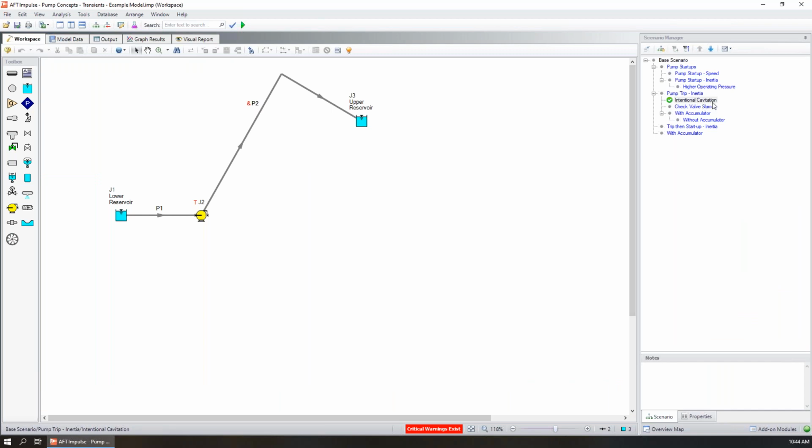So just a good example from a logical standpoint, from a physical standpoint, considering the system. If you remove this driving force, what the fluid wants to do is it wants to drain out this way, but it can't do that because there's not enough supply flow on this side. So instead what happens is the pressure drops at this point, it'll cavitate, and then that'll continue supplying this flow rate because it wants to continue draining. Again, critical warning, don't ignore warning messages. Be sure to read them, work your way through them.